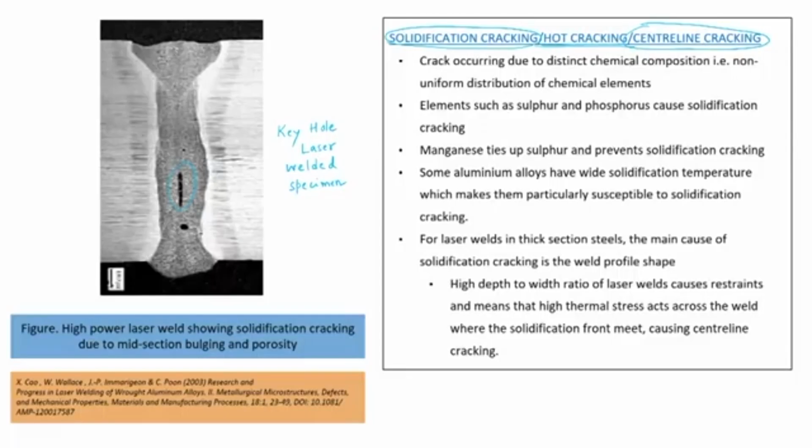When these elements are thermally processed, due to their material properties we may not get uniform expansion of these elements, which leads to cracking or defects during the laser welding operation.